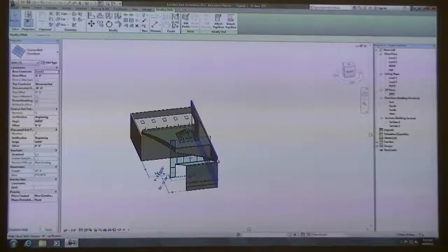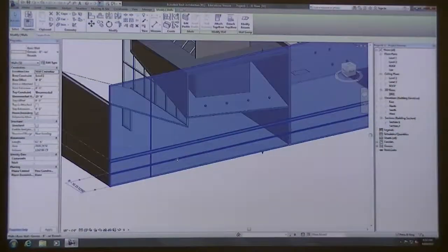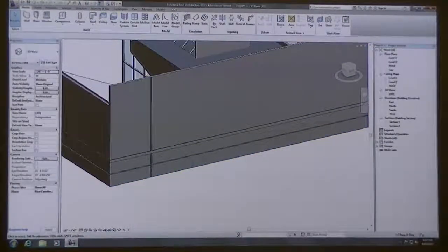The next part I want to talk about is, and so again, we can only do that in straight up and down walls. So that might be something good for the interior of your hotels, since we've got more complicated structures that have to do with the facade. Your facade systems are going to be articulated with the tools that you already know about, which are your curtain panels and your adaptive components and those type of divisions that you can do to the mass element.